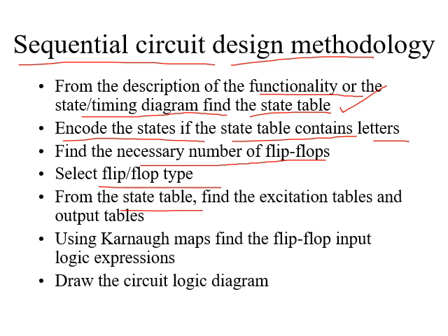Then from the state table, we find the excitation tables and the output tables. These will help us in determining the output expression and the next state expression. Then to simplify the expressions, we use the K-map technique. We can use any other technique as well, but the K-map technique is efficient. And finally, when the expression is obtained, we draw the circuit logic diagram. So these are the steps we can follow in designing an FSM.